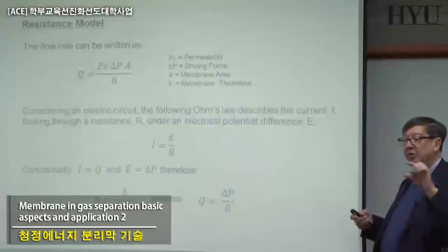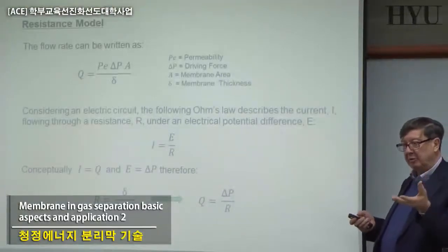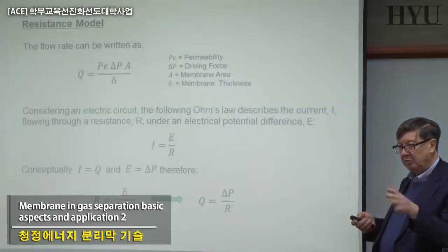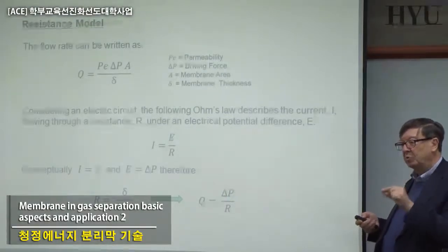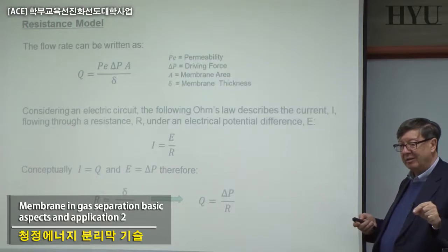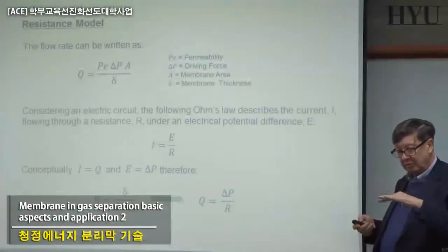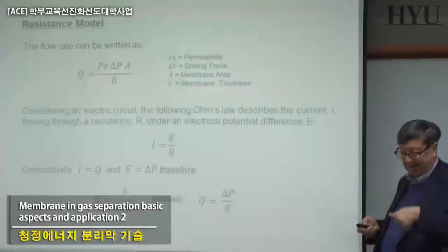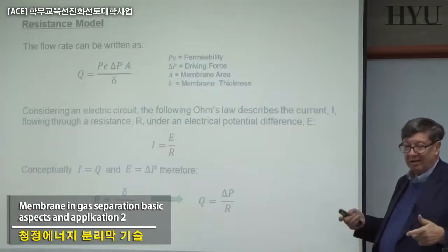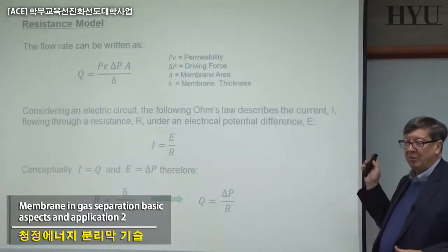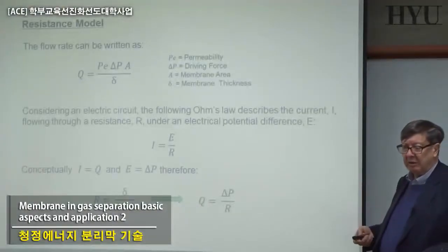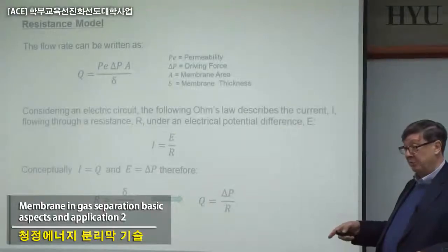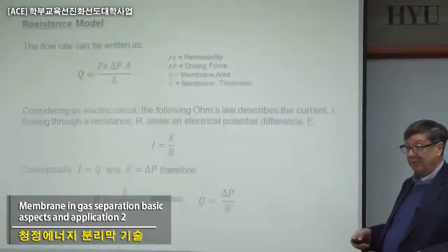So you have composite membranes based on the glassy polymer, polysulfone, and something that is trying to decrease the number of defects. This is a rubbery material coating the surface and basically plugging the holes which can exist. That is the way in which Prism made a patent years ago in the early 80s, and all the first membranes and most of the membranes that we use today are based on this.